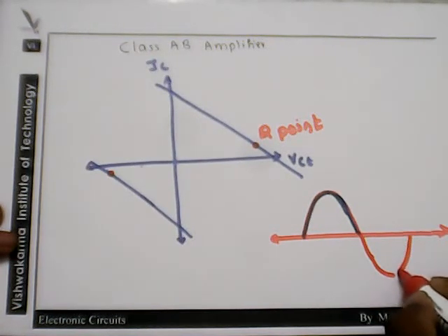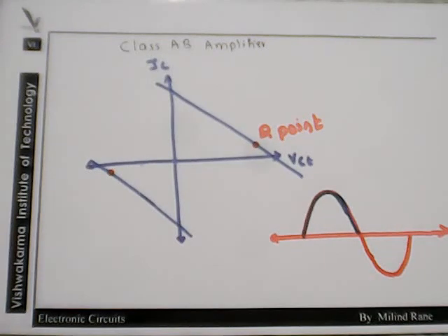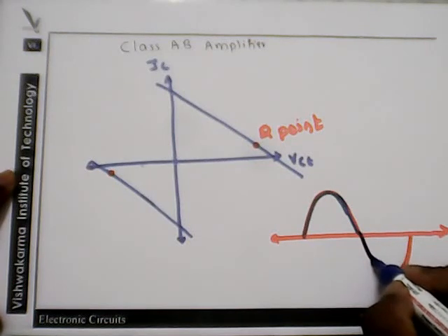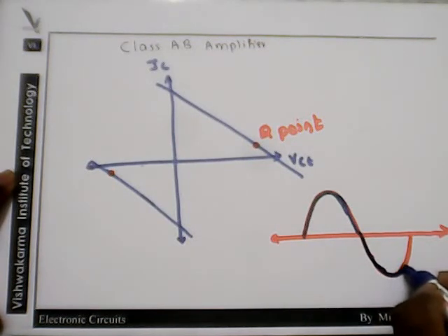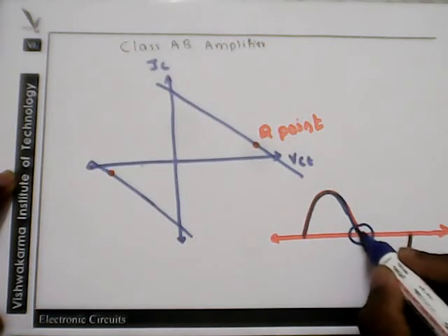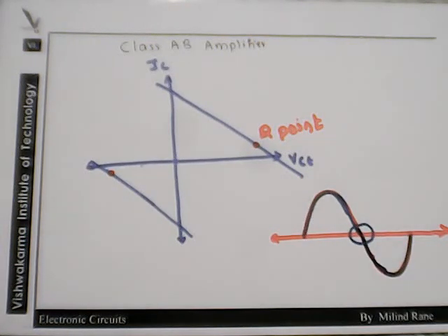There we get the output voltage waveform, as shown here by the blue line, and we can see that during the 0 crossing there is no distortion present, as one of the transistors gets turned on while pushing the other transistor to the off condition, and hence a smooth transition takes place, and we are able to remove the crossover distortion from the given amplifier.